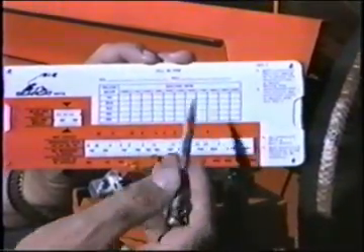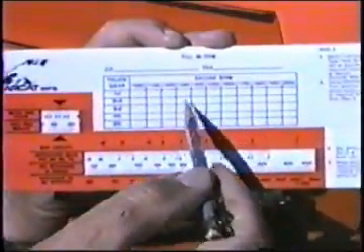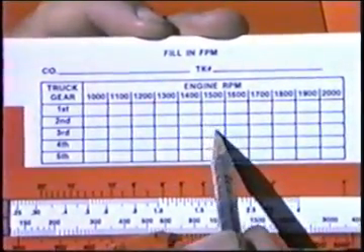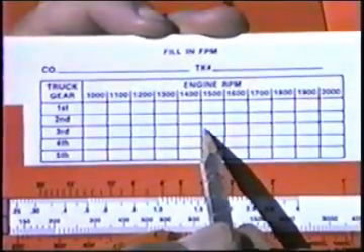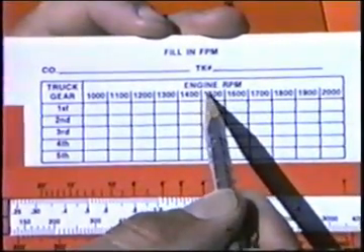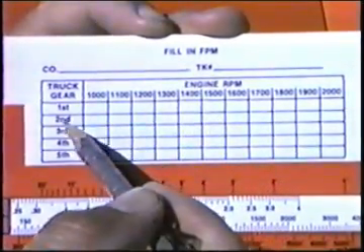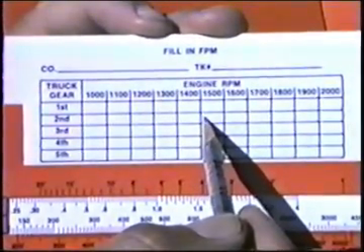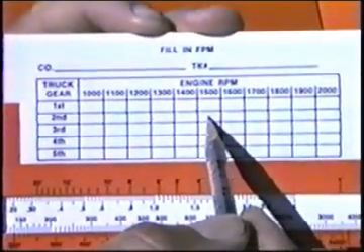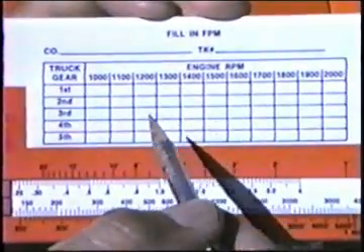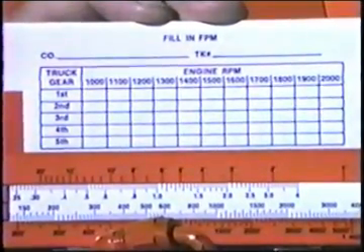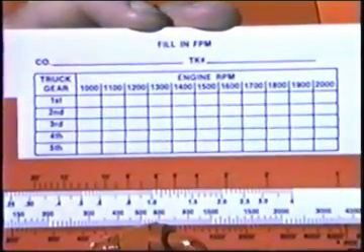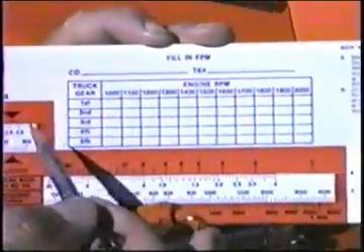side 2, the area that's not filled in here would be for a specific truck. That is, if it were filled in for this truck, each of these squares would be filled in with a travel speed in feet per minute. That is lining up with 1500, and if we had it in the second gear, if we line those 2 columns together, here we would read the travel speed in feet per minute for this particular truck. We fill those in for each truck when the truck is built. That scale can be used in setting up the spread rate, as well as it can give you a check to see that your instrument is right as far as feet per minute if there's some question about that.